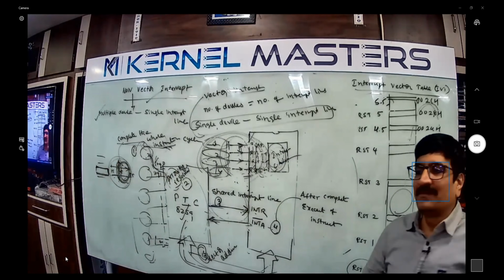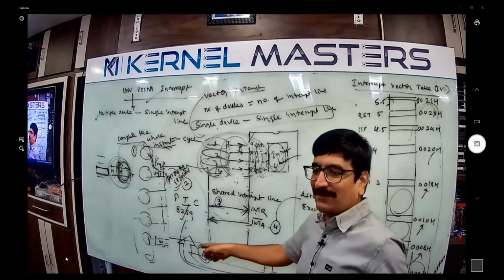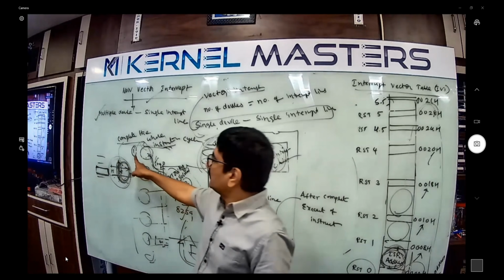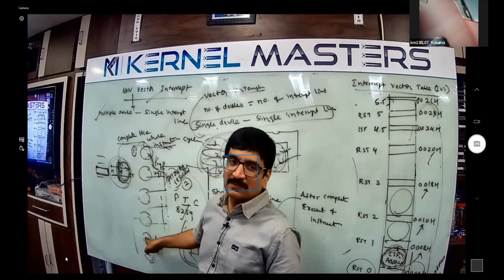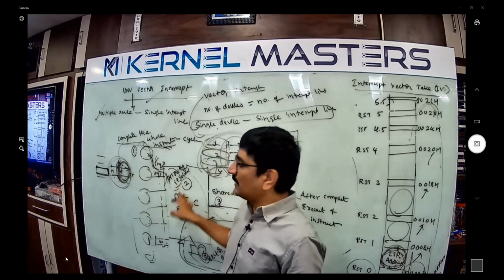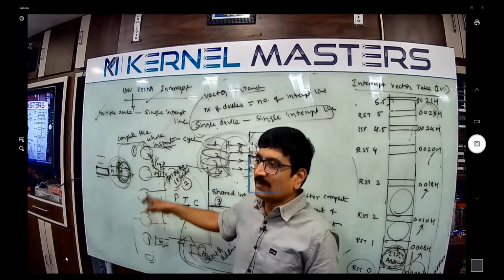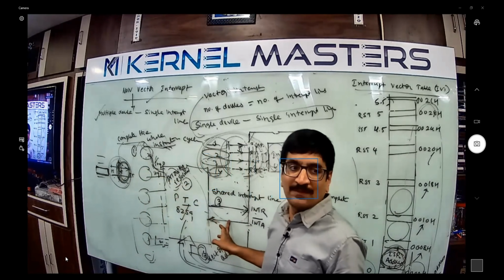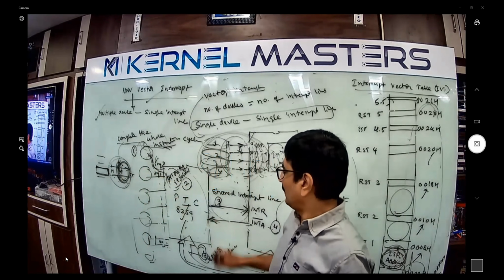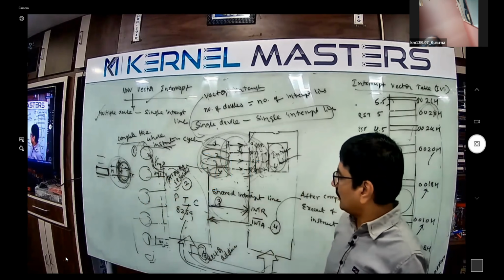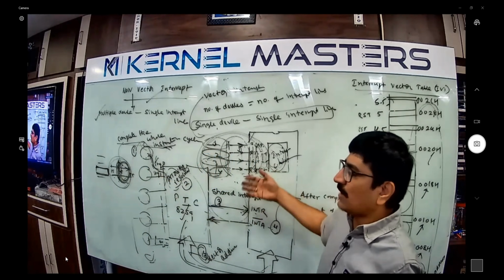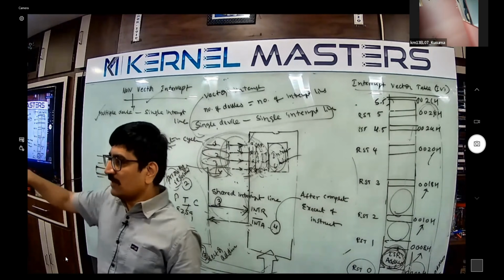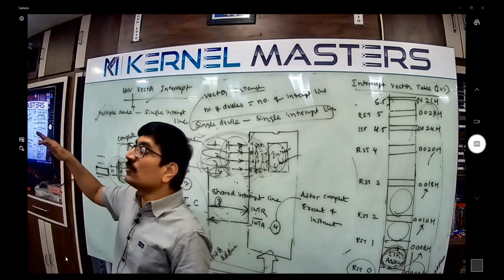Understood everyone? There are 5 steps. What is the first step? The starting step is raising an interrupt. Then the PIC verifies the priority. Only a high priority interrupt is allowed. Whenever it receives a high priority interrupt, any interrupt, not only non-vector but vector as well, the microprocessor acts after complete execution of the instruction cycle.